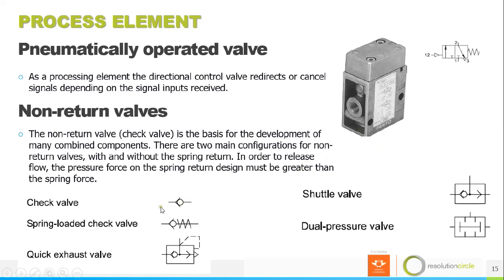There are 2 main configurations for non-return valves, with and without spring return. In order to release flow, the pressure force on the spring return design must be greater than the force of the spring. Let me start with this check valve.